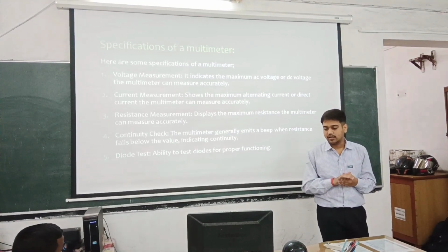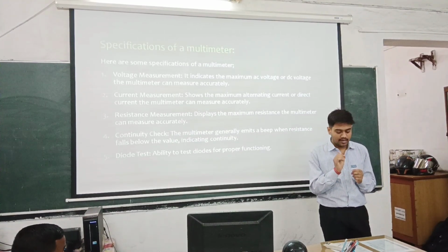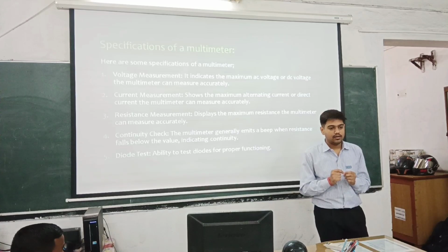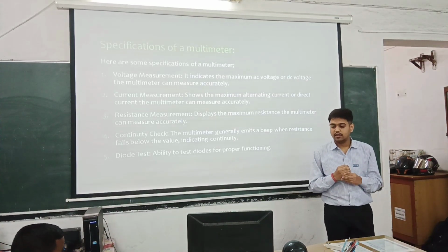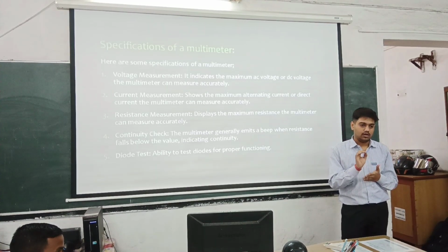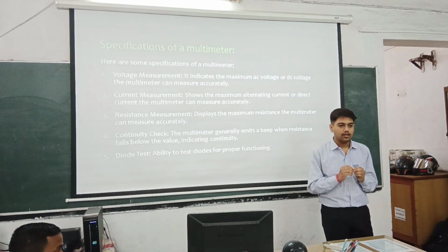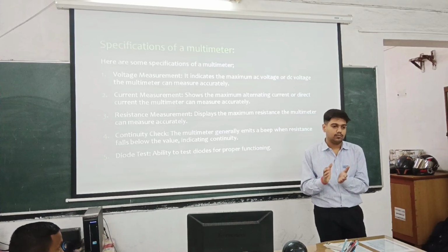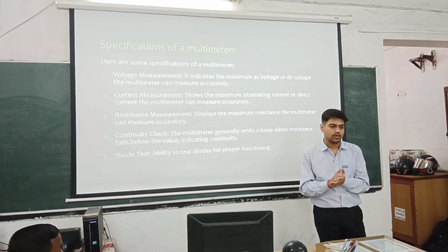For the continuity check, the multimeter generally emits a beep when it detects a continuous path. And lastly, we have the diode test. It has the ability to check whether diodes are working properly or not.